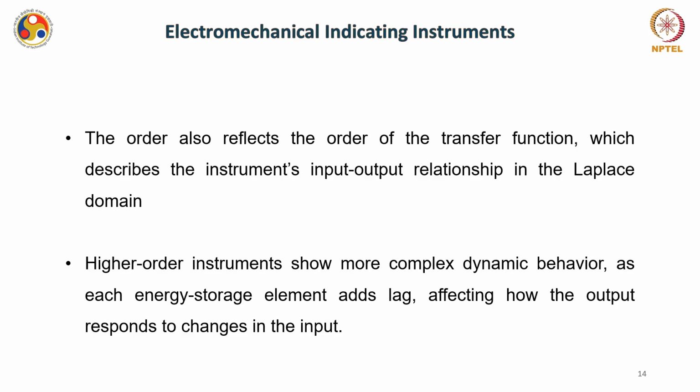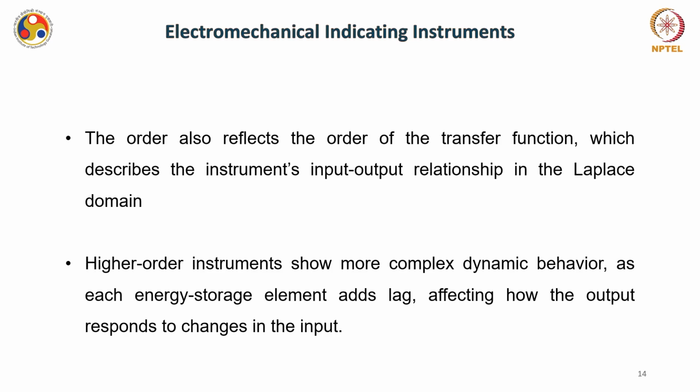Now this order also reflects the order of the transfer function, which describes basically the instrument's input output relationship in the Laplace domain. So if you have the transfer function of the instrument written in the Laplace domain, you can also find it via that. Higher order instruments show very complex dynamic behavior, as each energy storage element adds basically a lag, which affects how the output responds to changes in the input value.